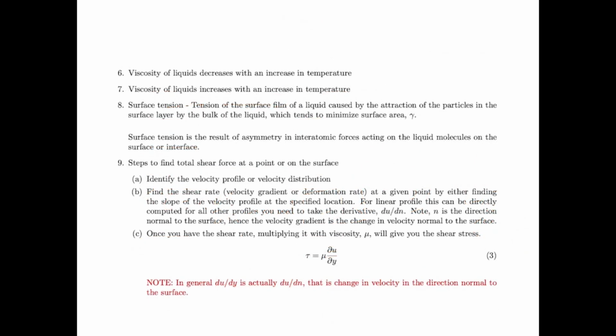A couple of things that we discussed is how the viscosity changes with temperature. So for a liquid, it decreases with increase in temperature, because when the viscosity decreases, you're saying the internal resistance has decreased, right? So a hotter liquid like oil or let's say honey will move more freely because the resistance has decreased, so the viscosity has decreased.